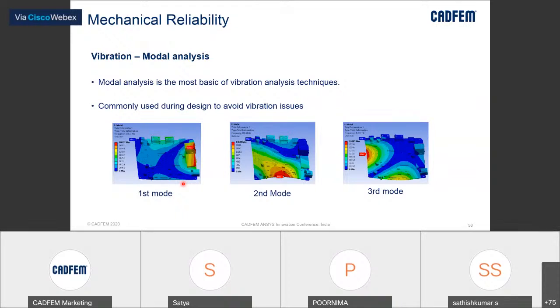Or it might be inside biomedical equipment. If it is static, properly fixed, it's okay. But if it is under dynamic pressure, and we have to move it to a different location and all that, this will create resonance. So in order to handle that, we have to do the modal analysis for the basic vibration analysis.